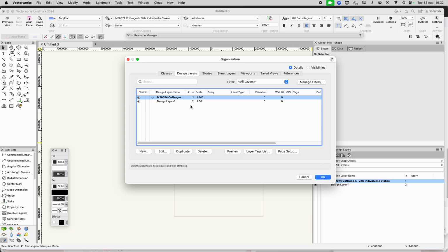I am not going to talk about this because it's a whole other thing that is potentially incredibly confusing. All that matters is that I need to be drawing at the same scale as the site survey. This site survey has come in at 1 to 20,000. That number is irrelevant because at the design layer, it's always 1 to 1. So you're just going to have to take my word for this because it would take me 10 minutes to explain it in a coherent way.